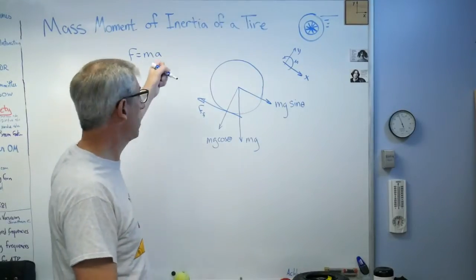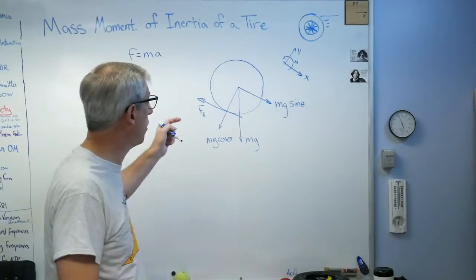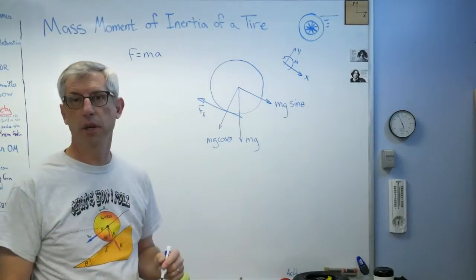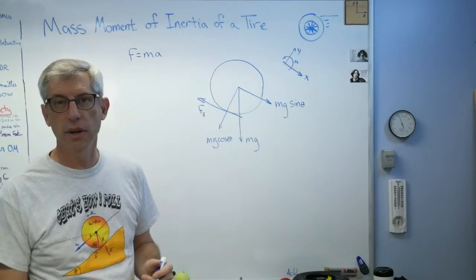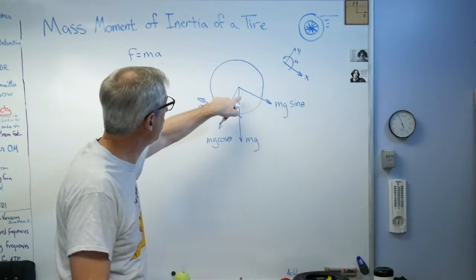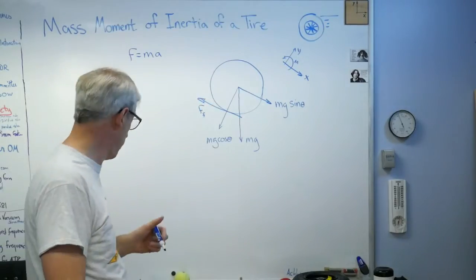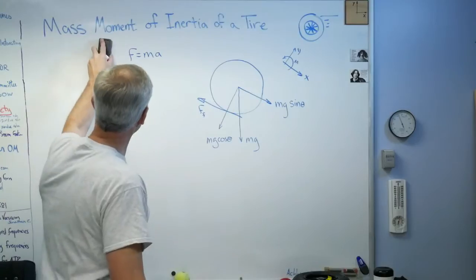But if I treat it like a force and push it around like a force and draw it on my free body diagrams like a force, I always get the right answer. So we teach our students to draw that inertial force on the free body diagram as if it was an external force. And guess what? You always get the right answer.